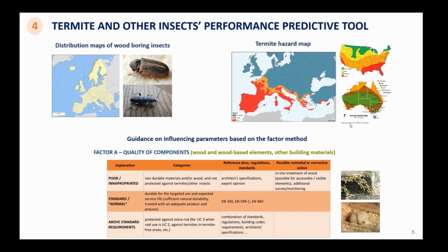Prevention of insect attack is always preferable to remedial control. This can be proper architectural design, avoidance of construction details that may trap water, efforts made to ensure that structures prone to termite infestation can be easily inspected. In order to help architects, designers, builders to anticipate and manage the insect risk, a guidance tool to handle the parameters influencing the insect risk has been prepared within the project.